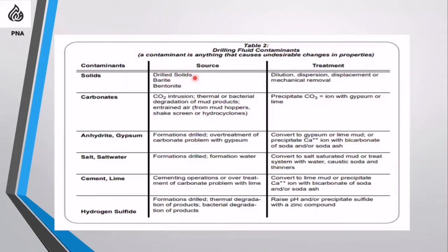For drill solids, the treatment is dilution by fresh mud, or mechanical removal by solids control equipment, dump and dilution, or mechanical removal.